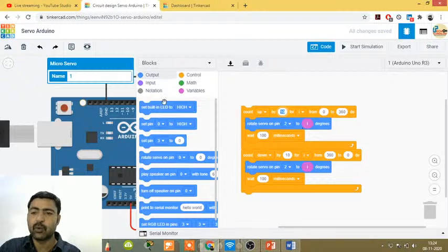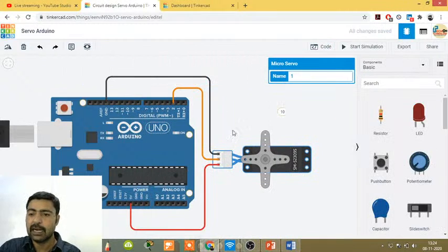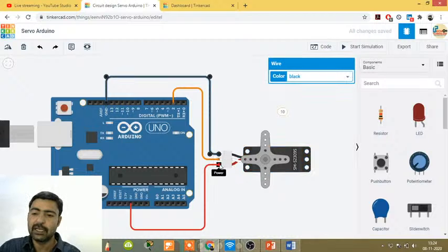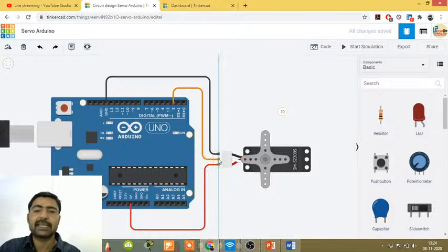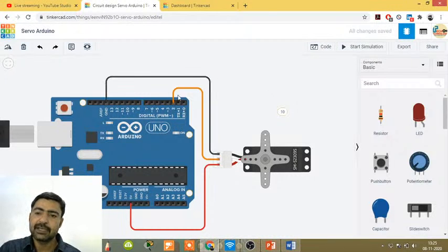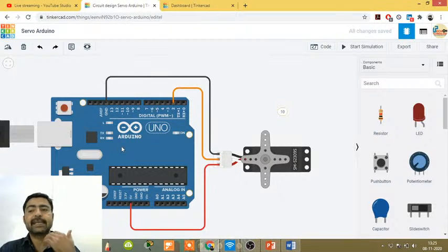And you are seeing that pin 2, because this pin 2 is connected to the Arduino servo pin 2. So this servo has 3 pins. This ground to apply 0 volt, this red to apply 5 volt, and this middle pin is to send the signal, the pulses. It will send the signal to the servo motor to operate it at different angles. So there are ways internally this Arduino board sends signals to the servo motor to operate it at different angles.